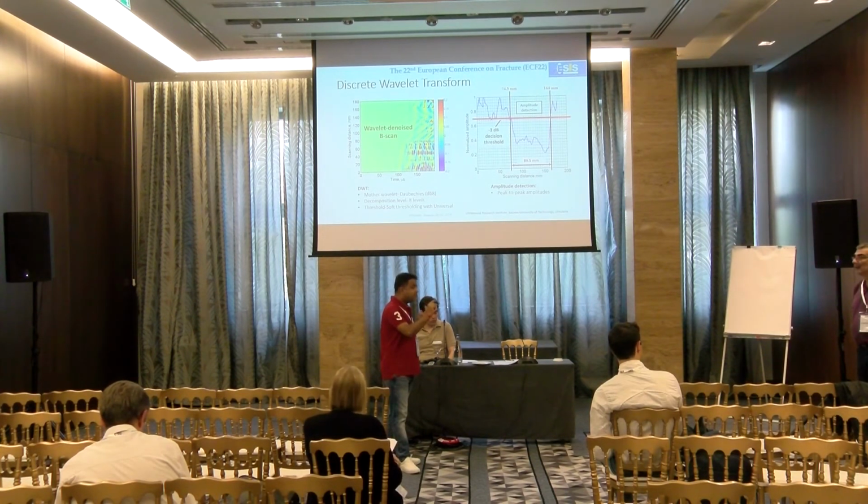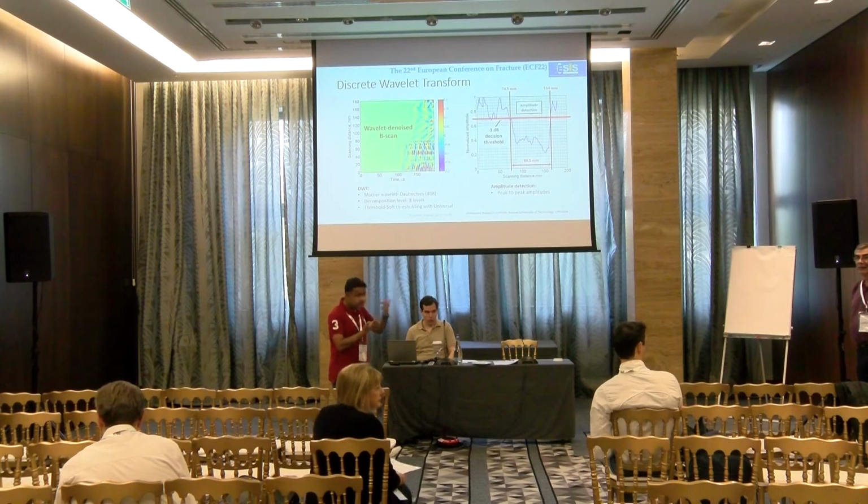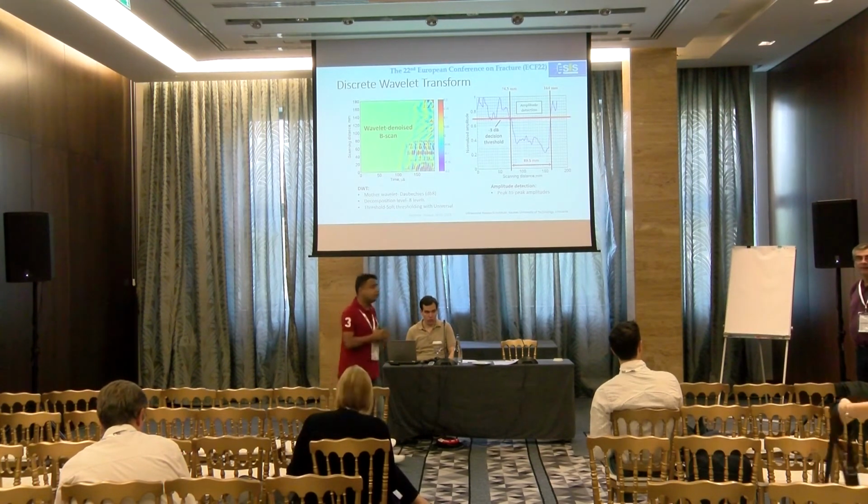The wave of interest was only the A0 wave, out of plane, because the receiver was a point-type thickness mode receiver, which is more sensitive to out-of-plane radiation. So our focus was only on the out-of-plane waves. Then we applied the DWT for denoising to extract the size and location.